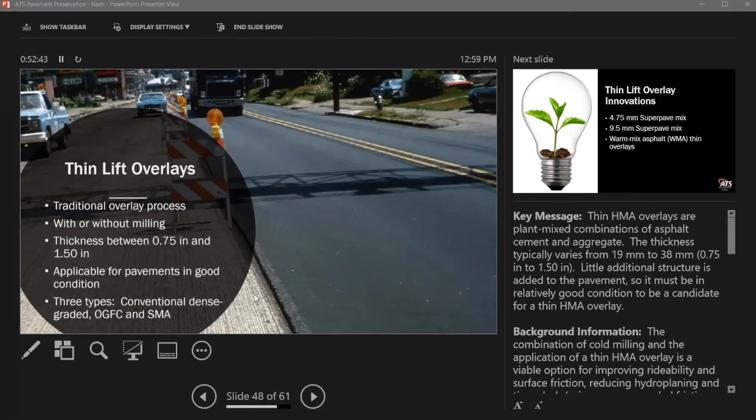Yeah, so your top 3/8 of the pavement, you're looking at rejuvenation. Crack sealing doesn't actually rejuvenate. You can penetrate the top 3/8, but you can also go down a little bit farther than that depending on how far you cut. But the primary part of that question is reducing binder viscosity. That's the sole purpose for the rejuvenation. So that's kind of what we're looking for. All right. Very good, thanks.